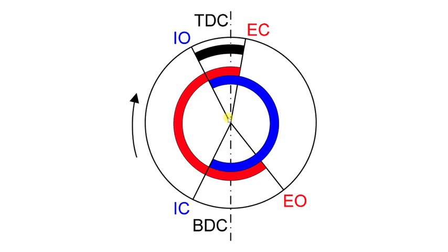So our piston's going to come towards top dead center. You can see the crankshaft rotates around, the piston's being pushed upwards, and then at this point here, the air inlet valve is going to open. It's then going to draw air in as the piston moves down and the crankshaft rotates clockwise. The piston reaches bottom dead center, comes around here, so we're looking at about 200 degrees.